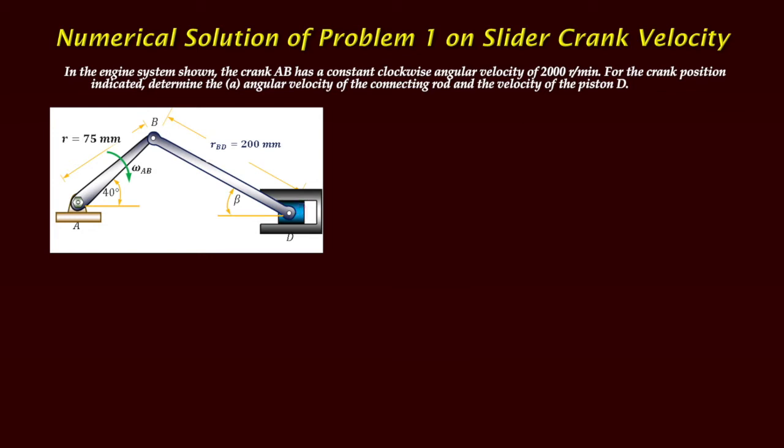So we need to convert this reciprocating motion to circular motion, and that is done by this type of mechanism where the piston and the wheel are linked by these two links AB and BD. This link AB is called the crank, and this particular link BD is known as the connecting rod.